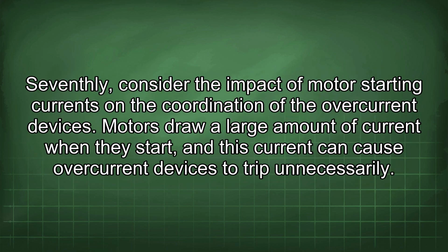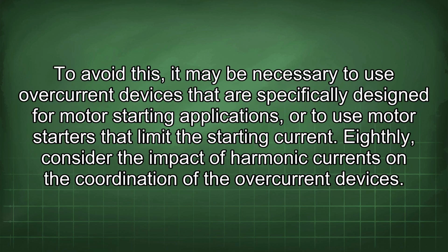Seventhly, consider the impact of motor starting currents on the coordination of the overcurrent devices. Motors draw a large amount of current when they start, and this current can cause overcurrent devices to trip unnecessarily. To avoid this, it may be necessary to use overcurrent devices that are specifically designed for motor starting applications, or to use motor starters that limit the starting current.